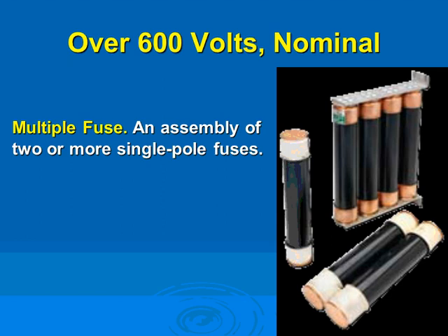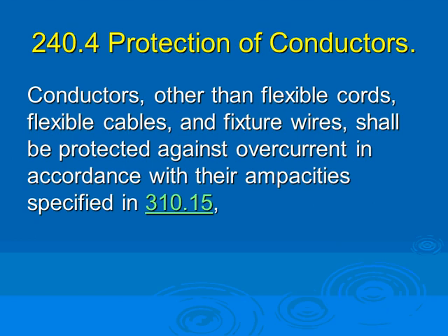So, assembly fuses, okay, flexible conductors. When it comes to protecting, overcurrent protection device guys protect conductors based on 310.15. You guys are familiar with 310.15. For example, a number 14 conductor cannot be protected with an overcurrent protection device of more than 15 amps.